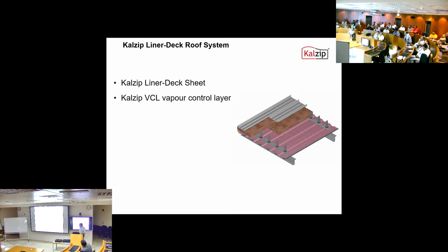Because of the way the system works, it achieves better U-value performance, so we introduce a top hat section, a mega section. This profile, due to the geometry of the profile and the structural capacity, isn't modular with the calcium outer sheets. So it's slightly different than the liner system, which is modular. We introduce the top hat so we can install the clips to pick up the standing seam. So it's a flexible system for achieving thermal performance by increasing the insulation depth.